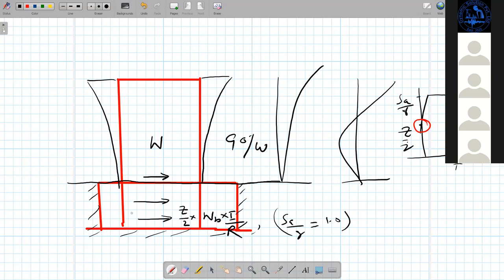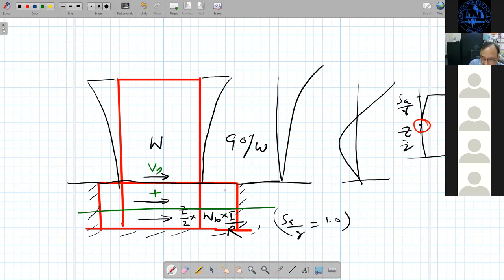So that weight you will take, and then for the bottom portion, you will calculate. Suppose you want to calculate shear force at this location. You want to calculate the forces in your members. Then this will be your VB plus whatever force is acting in the upper portion of the basement above this, that you will add.